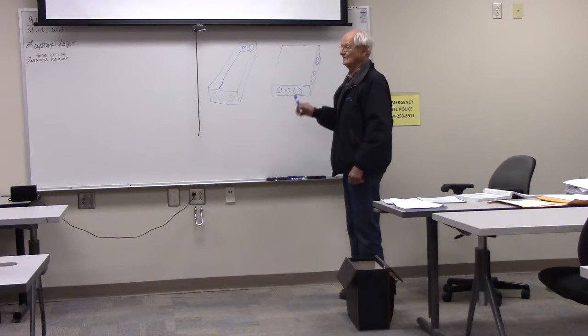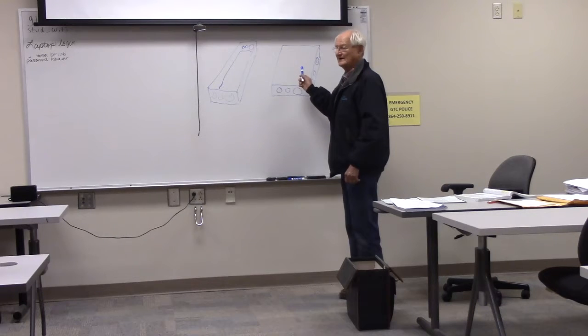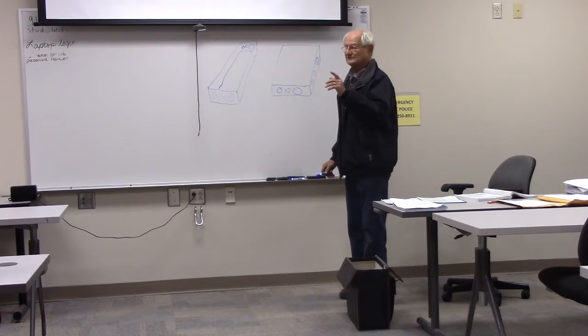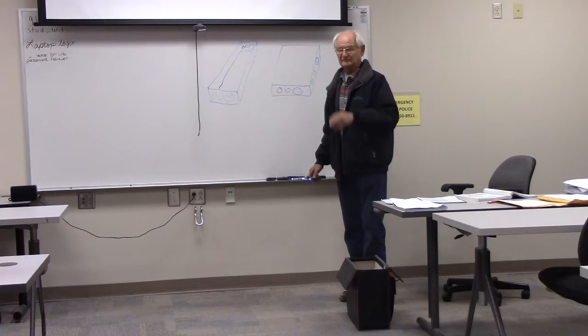Okay, so if you go in and turn out an angle, a wall on the side wall, it's 6 times the diameter of the largest raceway plus the accumulated total of all other raceways.